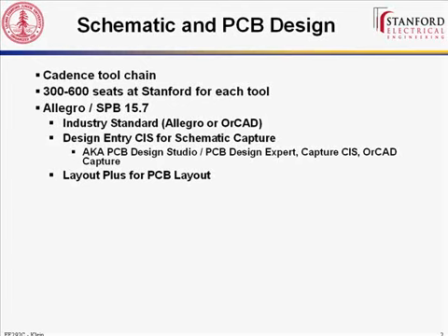If you use the XL option, which I recommended you do in your install notes, that becomes PCB Design Expert. If you use just L, it becomes PCB Design Studio. There's a minor feature set difference. For this class, it doesn't really matter either way. XL will give you some differential routing help and some things like that. The same program also is called Capture CIS or OrCAD Capture. So once you learn how to use the software in this class, you can use all of these programs because they're all the same.